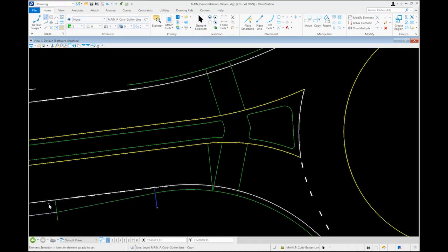So we ended up with a nice smooth taper that tied in directly to this entrance curve so that we end up minimizing the number of inflection points along that curb line and the number of unique geometric elements. So that'll set our curb line, and we'll end up with our curb line coming back at least to this point. Now, if you have an urban section, this curb line could easily extend along the shoulder instead.